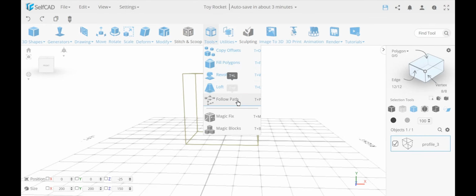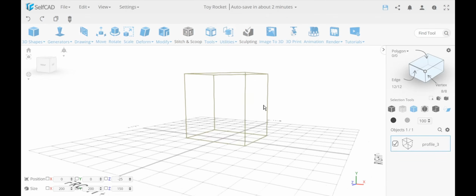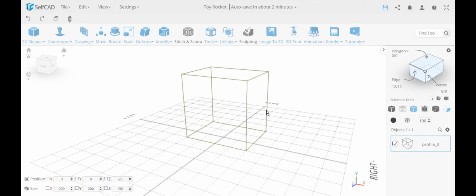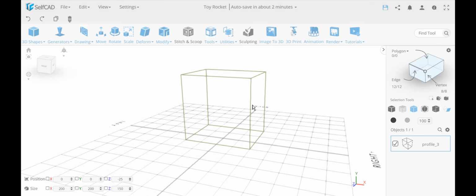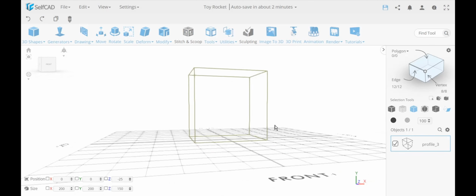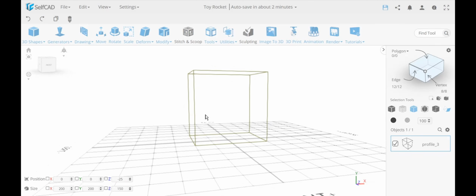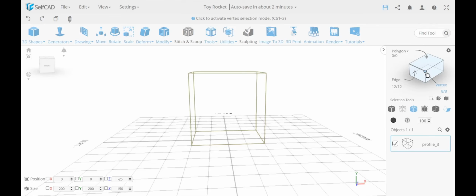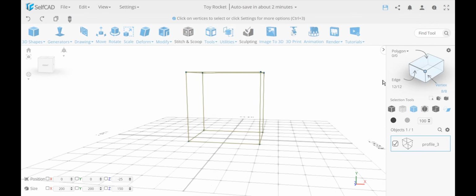But again, I hope to make separate videos for each of them. I just want to show you one example here. Suppose I want to make this kind of odd shape, and I need to draw this into a spline. So let's say this should be a spline. I can first delete this edge over here.